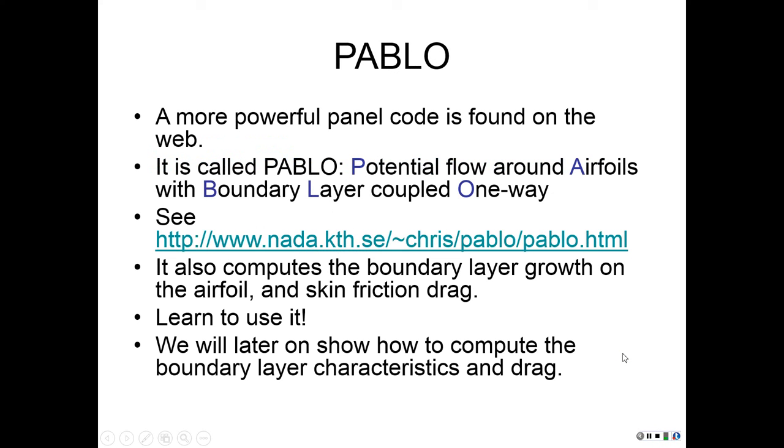There are other programs besides Xfoil. There's a program called Pablo that you could use. We don't use Pablo anymore. Most people use Xfoil. So we will show in some of our lectures how to use Xfoil to compute the lift coefficient and also the drag coefficient.